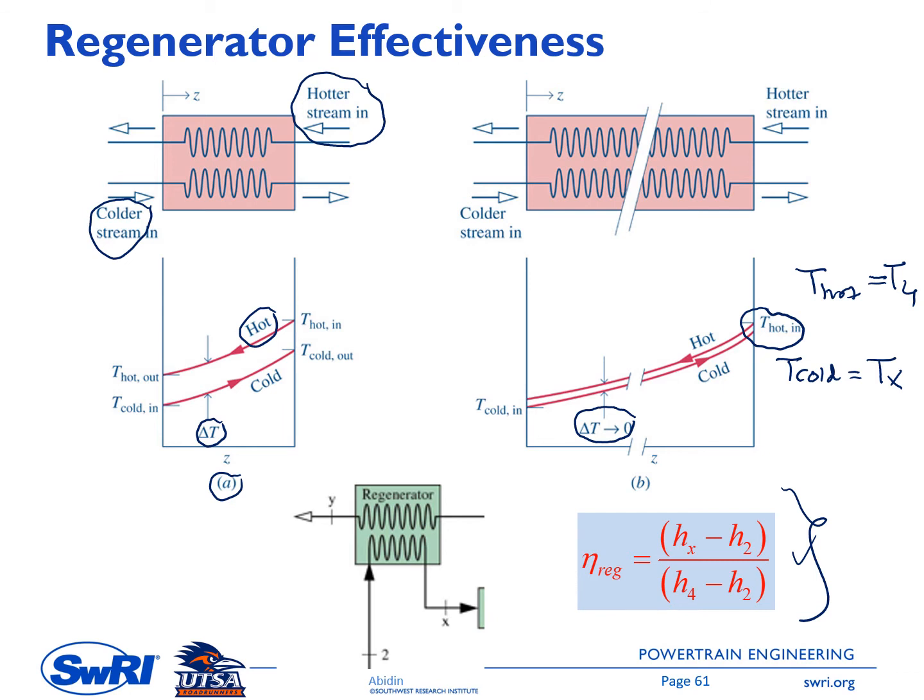So the addition of this heat regenerator to a gas turbine is finally limited by this pressure drop as well as the price of the regenerator, because a bigger regenerator costs more money. So at some point it might not be economic to include regenerator in a gas turbine, because the efficiency improvement is smaller than the increase of the capital cost.